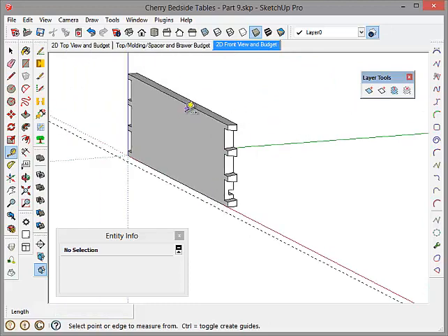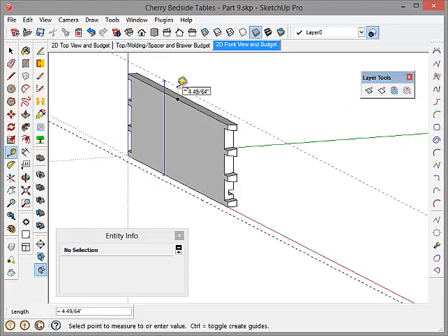Now remember that the draw opening was 4 3/8 and I made this 4 1/8. So there's another 1/4 of an inch or 4/16 of an inch of gap between the top of the draw box and the draw opening. So I've got to add that to 5/16, which will give me a total of 9/16. So I'll come up 9/16.